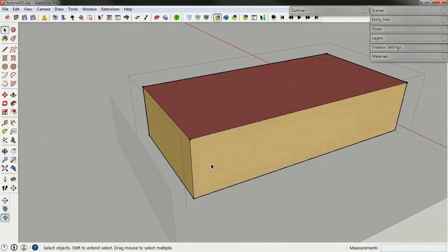So as a result of that, in order for it to know where a window is, the window must be completely coplanar, that is, in the same plane as the wall, and it can't extend to the edge of the wall. These are two rules that can't be changed. So you always, always, always must have a window within the wall.